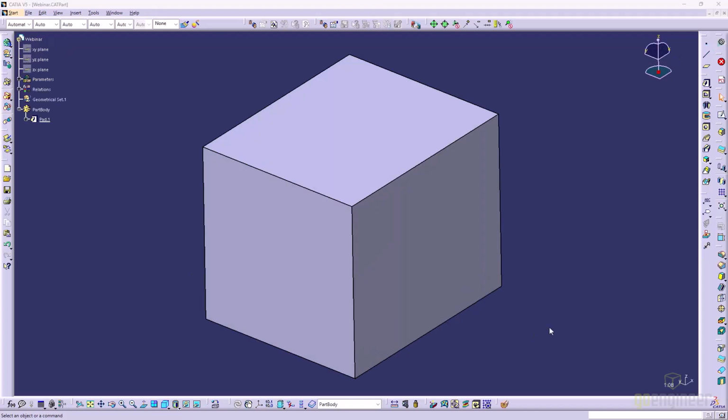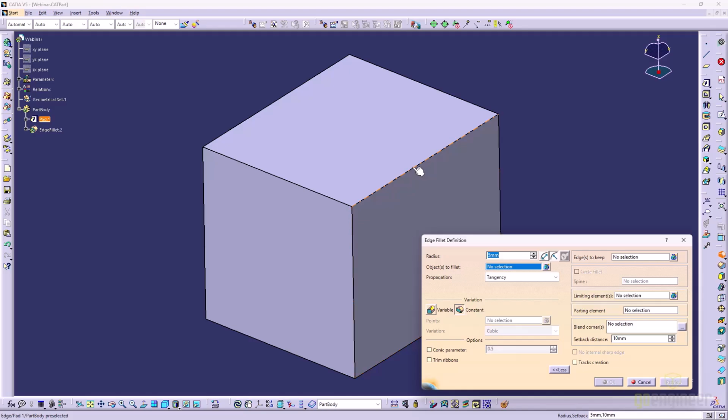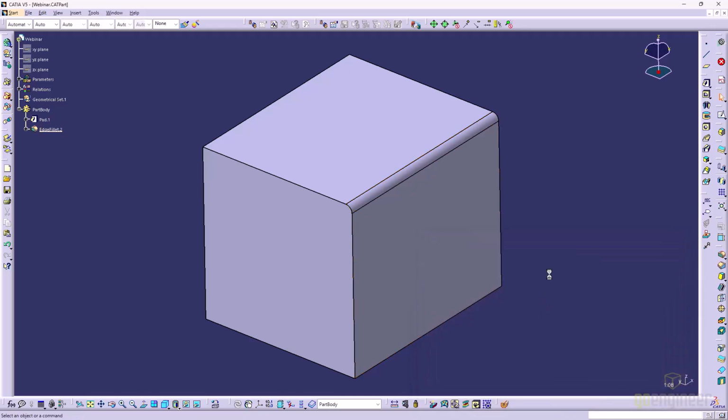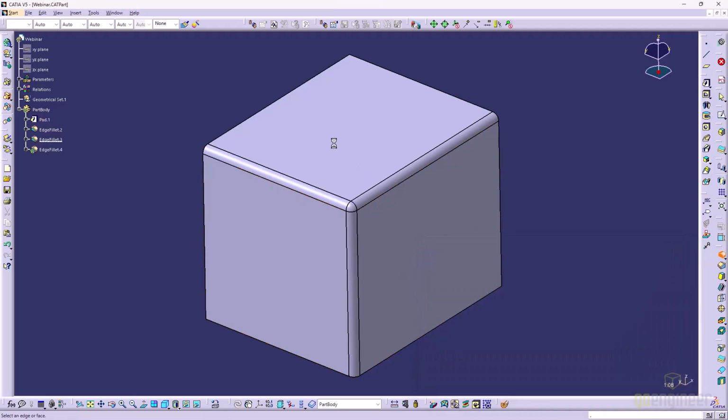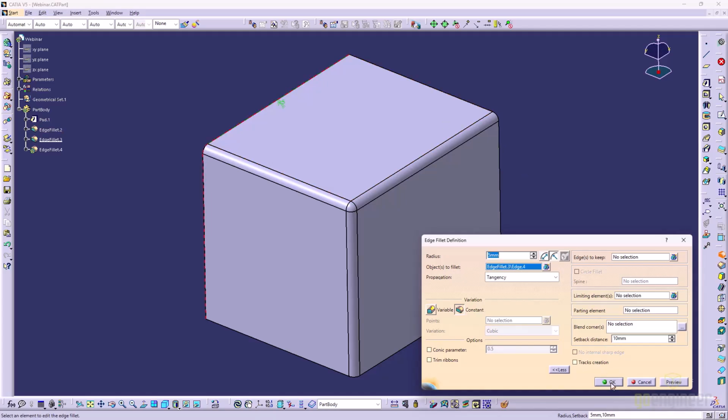Moving into CATIA use tips and tricks, we'll start with repeating commands. Simply selecting a CATIA feature will prompt the command to run until all the required information is input. Then the command will end. However, if you double-click on the feature, the command will repeat after initial information is input and will continue until you end the command with the Escape key.